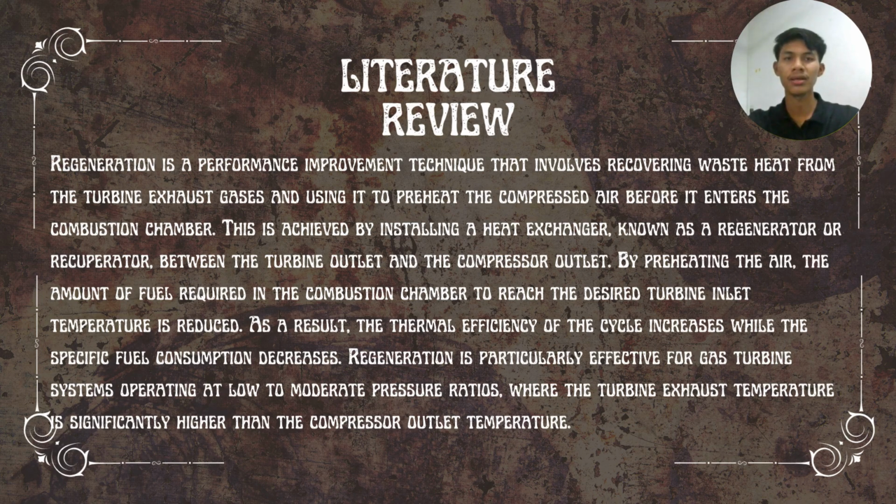Regeneration is particularly effective for gas turbines operating at a low to moderate pressure ratio, where the turbine exhaust temperature is significantly higher than the compressor outlet temperature.